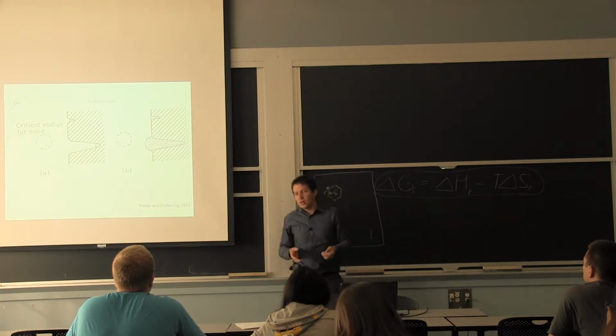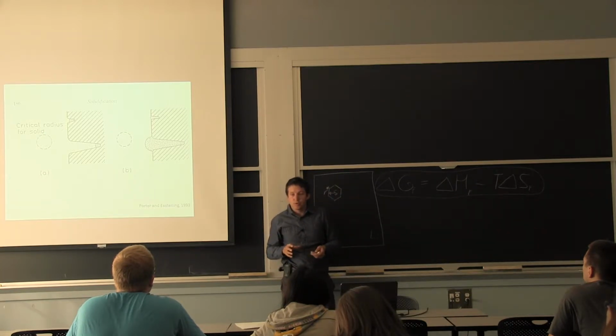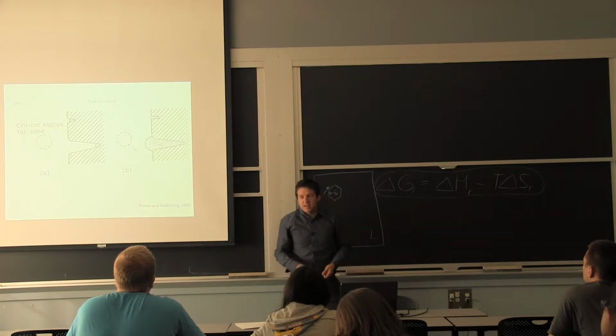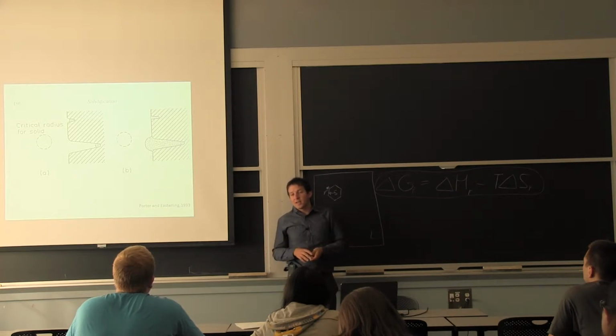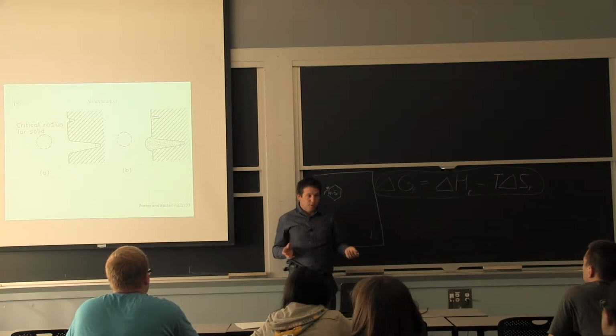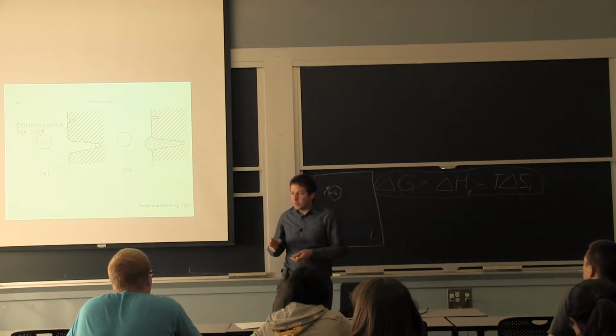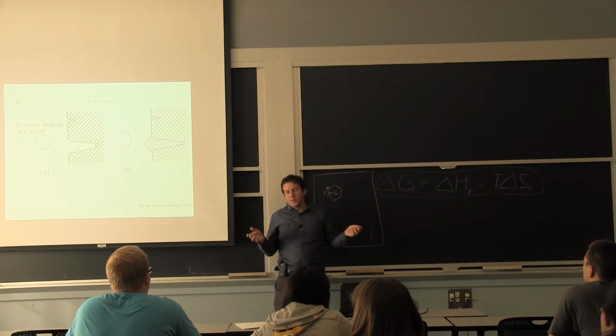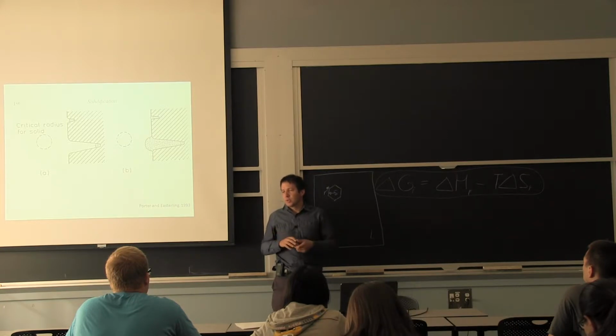It depends on exactly what your temperature is and what the energy is for changing the interface here from the liquid to the mold to between two solids. And that depends on the quality of contact, if you have a metallic mold, a ceramic mold, a sand mold. So there's a lot of variation. Your idea about using another crystal is by far the least amount of energy, because you just literally continue adding to the same structure.